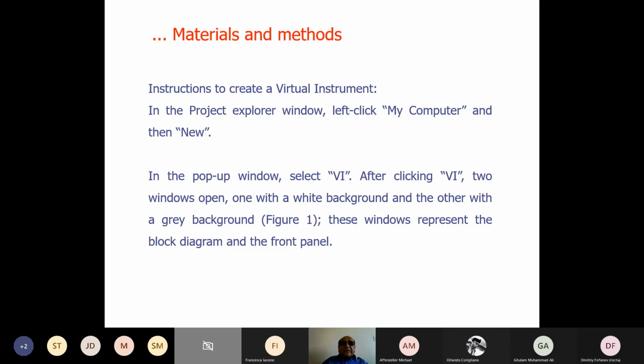Instructions to create a virtual instrument. In the Project Explorer window, left-click My Computer and then New. In the pop-up window, select Virtual Instrument.